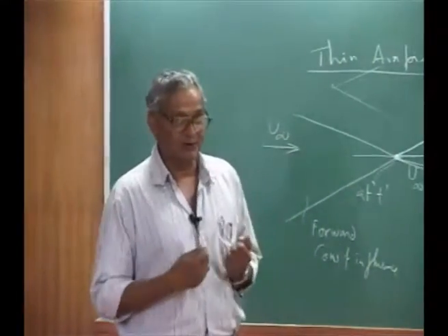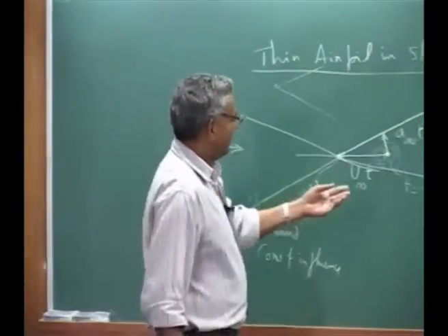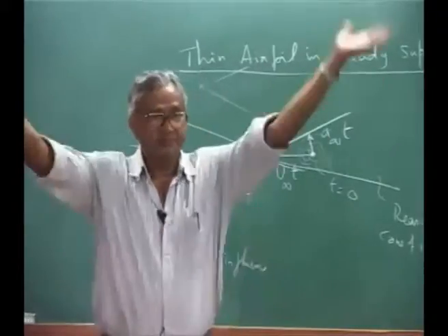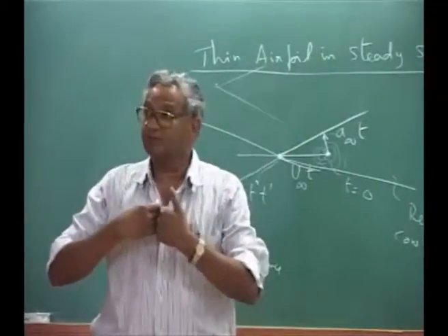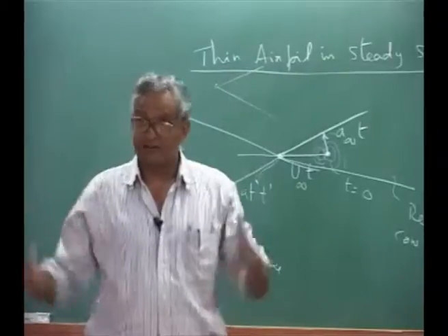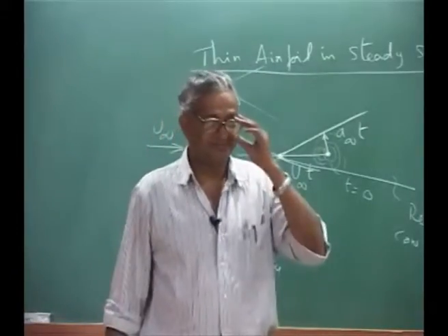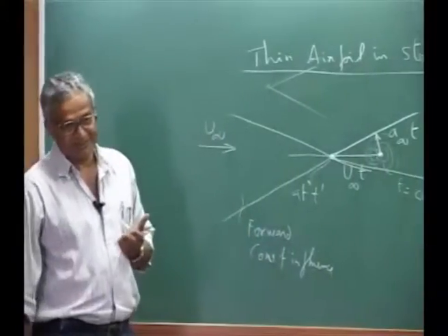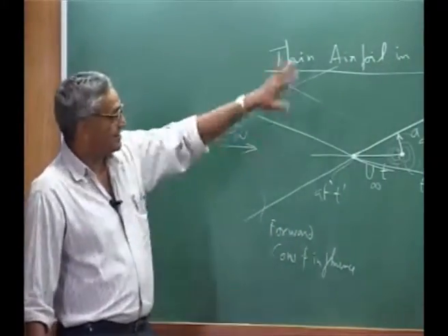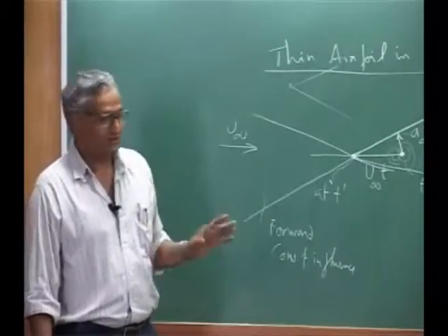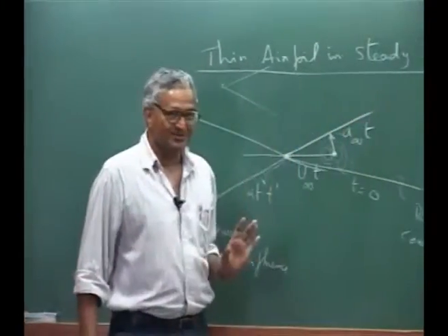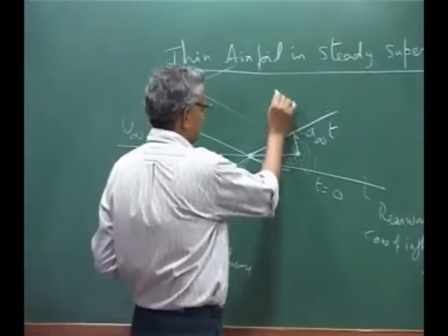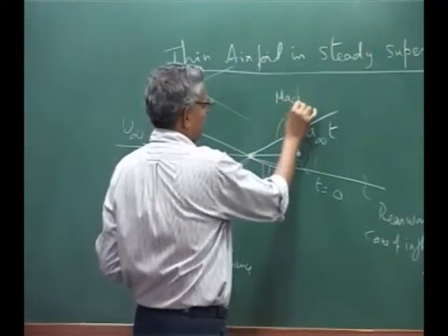Whereas in a subsonic flow, the body moves slower, whereas the disturbance moves faster. So it will go and affect the flow everywhere, and that will affect this also. Okay. So that is the reason subsonic flow is much more complicated, because the entire region will be affected, whereas in the supersonic flow only a restricted region will be affected. And this is called the Mach cone.